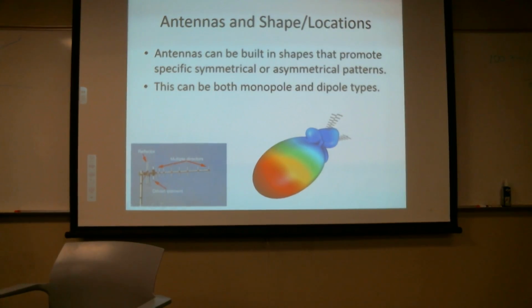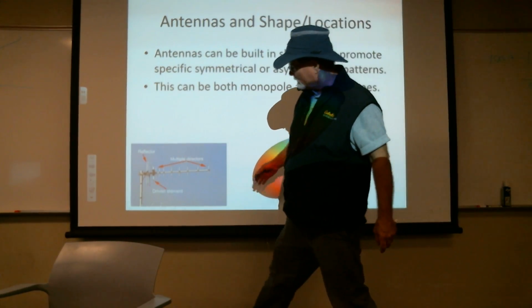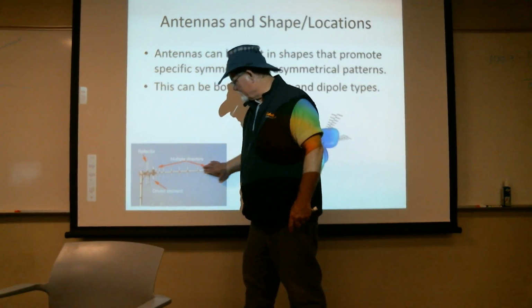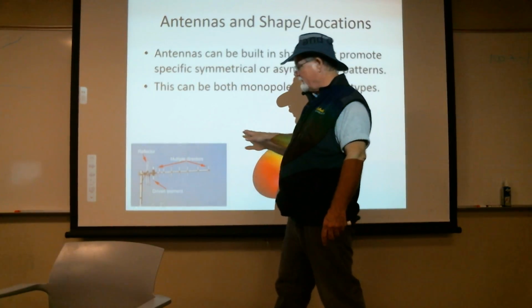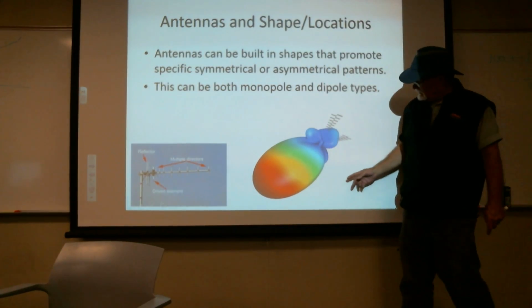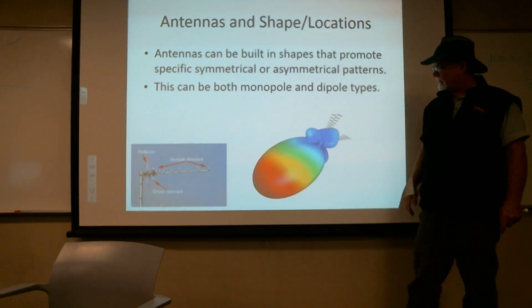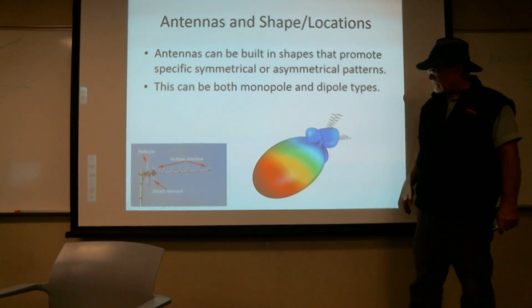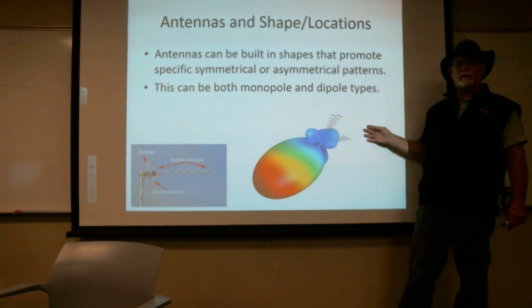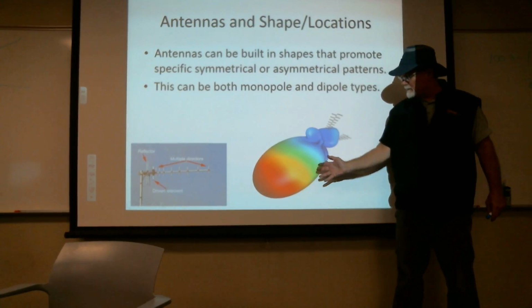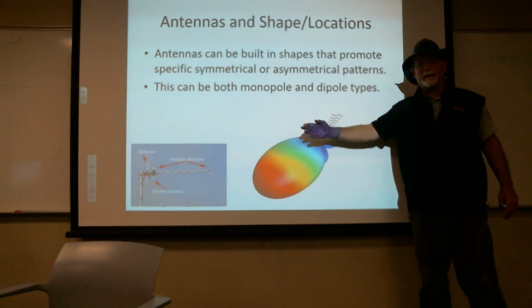So here's an example of a couple of antenna arrays. This one sort of shows some side reflectors this way, and then the driven element array that way. And that's going to try and make a big lobe coming out this way. Here, it looks like I probably got an array pointed this way, and then the two side lobe producers there, or your reflectors produced there. That's going to take a whole bunch of energy going this way, a little bit of backwash energy this way, and then because of this sort of cloud of energy, you're going to get some smaller lobes forming vertically, and maybe even a little bit coming out that way.